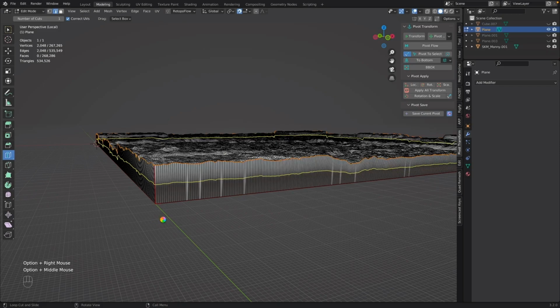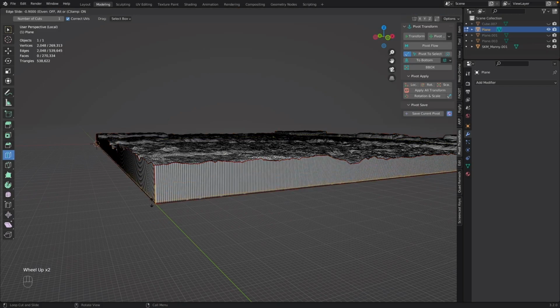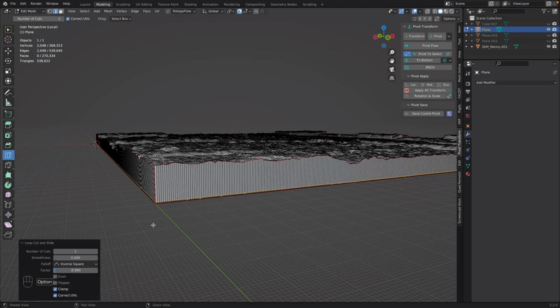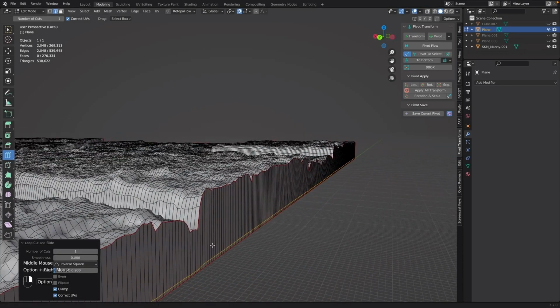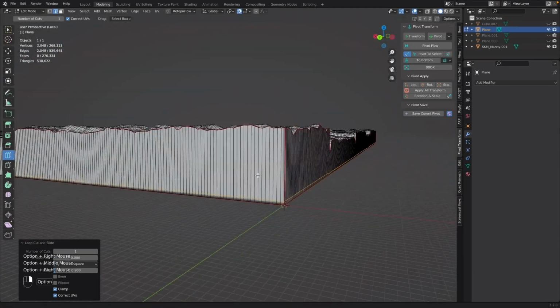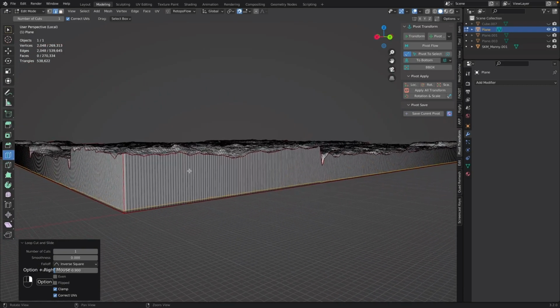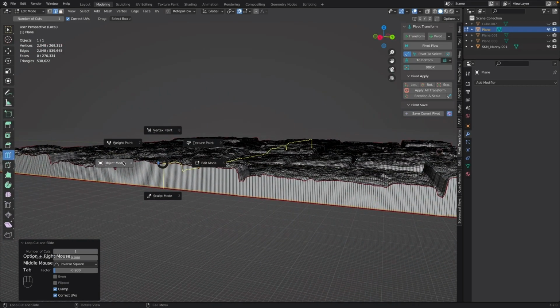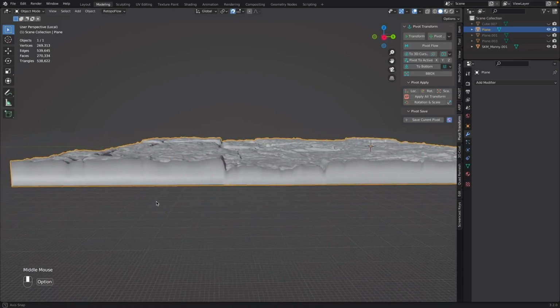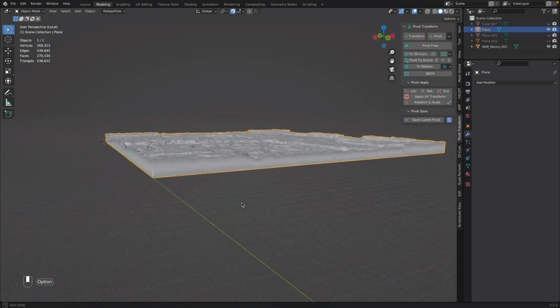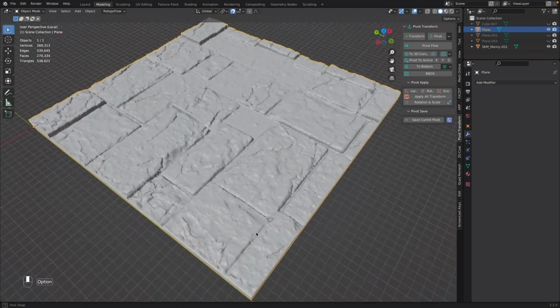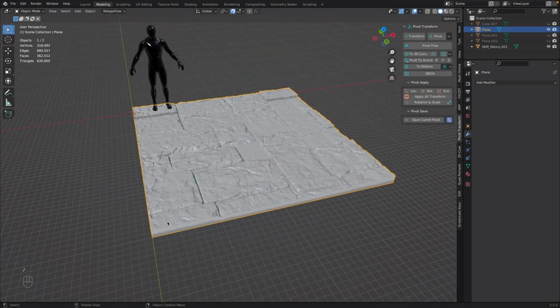All that's left to do is export this out. And for this, if you're not familiar, there's a great add-on called Better FBX Exporter that I'm going to use. What I love about it is that it already has some presets. For example, you can automatically select the Maya Z up for your axis. Another thing I found is in some cases, it actually works better with older versions of FBX files than the standard one from Blender does.